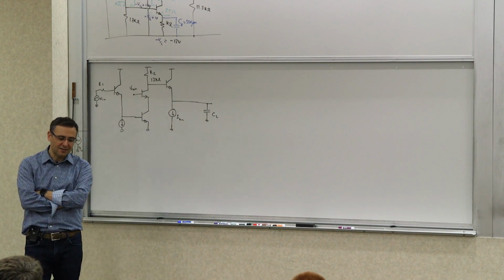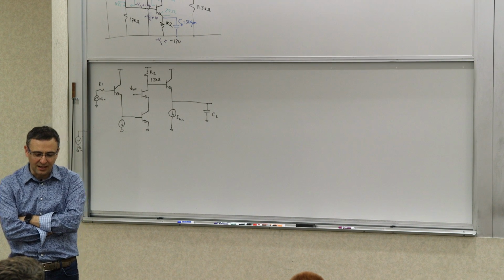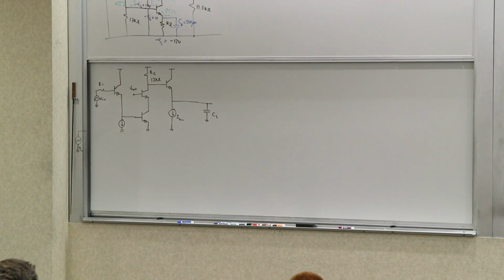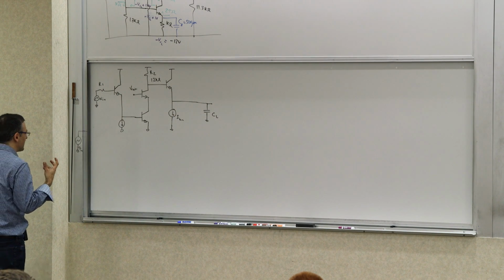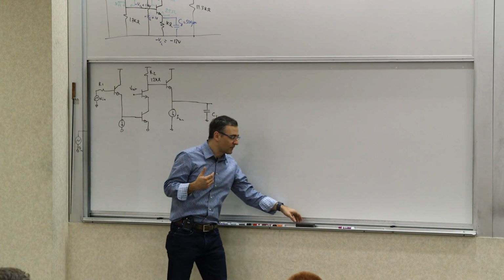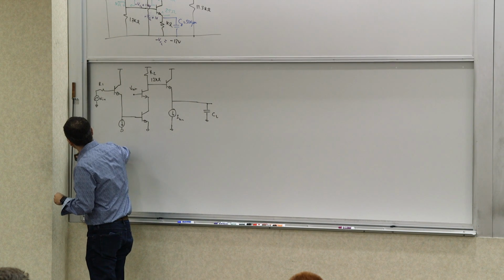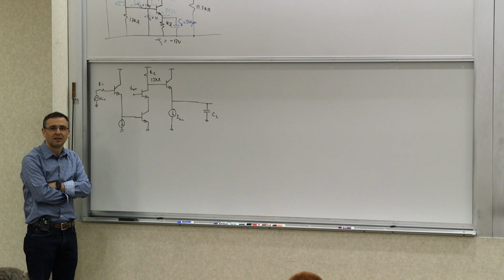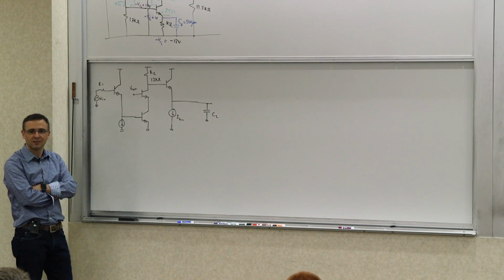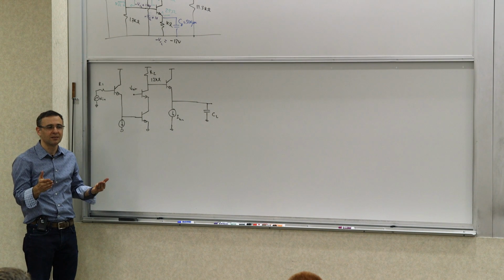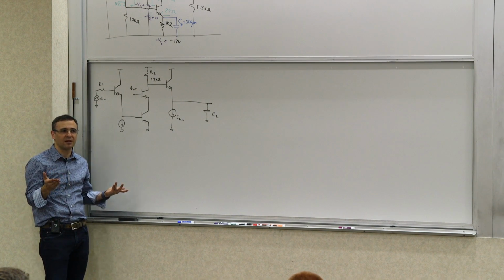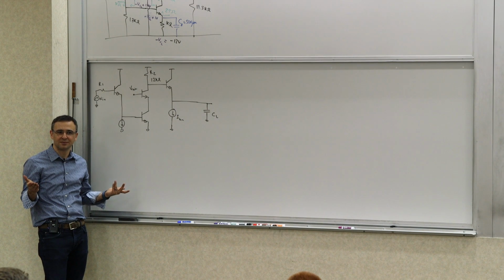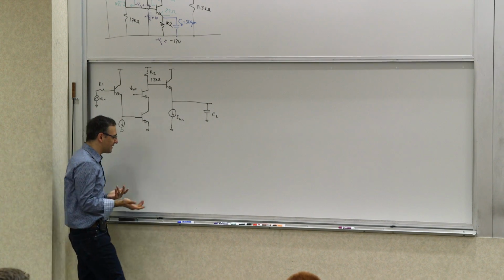But on integrated circuits, we can also do something which is useful. What is one of the realizations, or manifestations, of a common emitter in an IC configuration? It's the differential pair. If you think about a differential pair, the half-circuit equivalent of a standard differential pair is a common emitter. So we can implement it as a differential circuit.